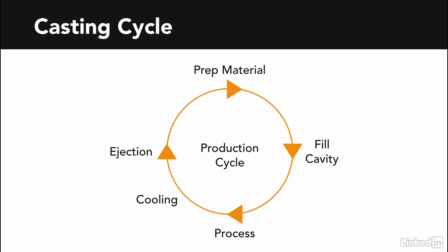This cycle is the end-to-end procedure for preparing the material, getting the material in mold, the forming cycle, and the ejection of the part. Factory cycles are much faster than prototyping, but involve a much higher initial cost, which is why full-scale manufacturing is generally reserved for designs that have had most of the bugs worked out prior to the creation of the die for high-volume use. Let's look at those steps now.